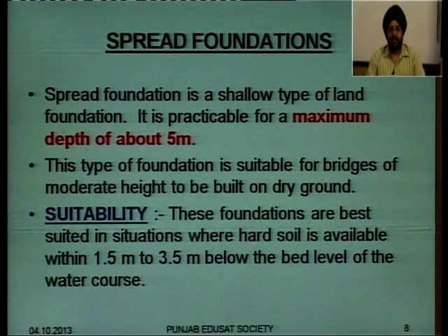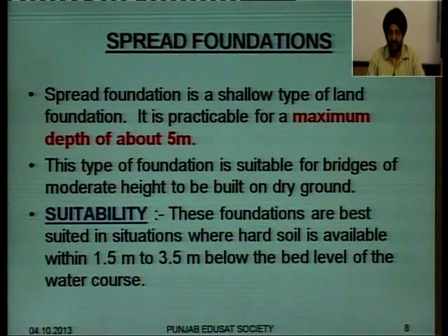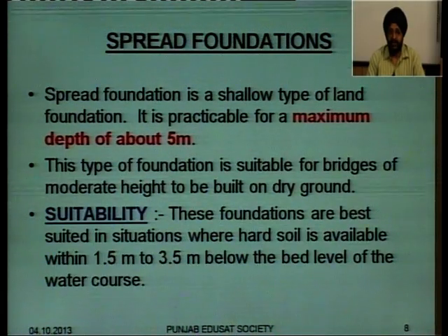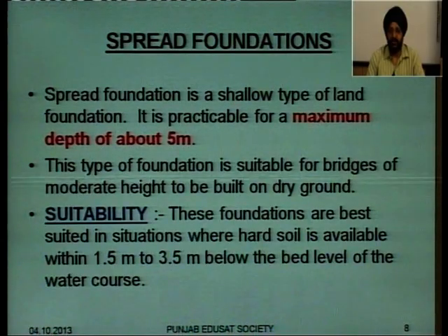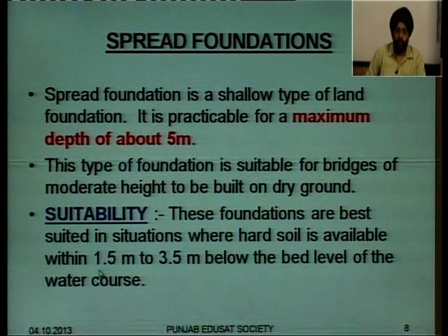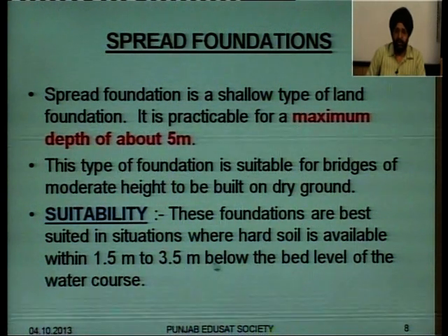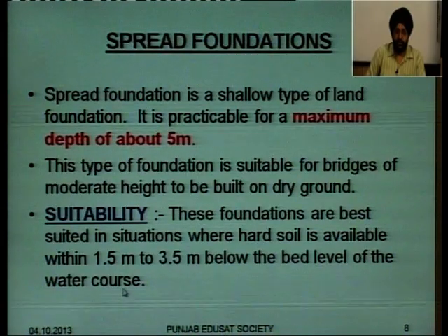These foundations are best suited in situations where hard soil is available. Now this is again important. Spread foundations are not meant for soft soils. These are best suited where hard soil is available, and that also within 1.5 meters to 3.5 meters below the bed level of the watercourse.